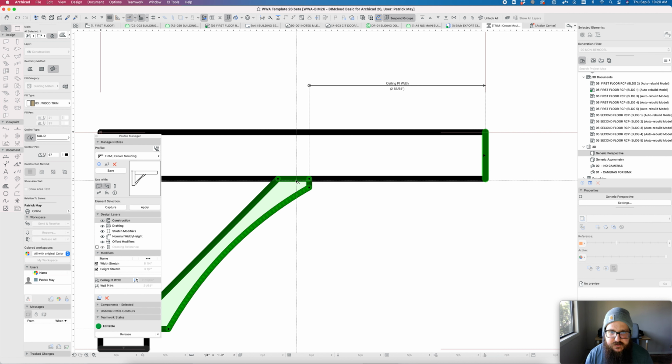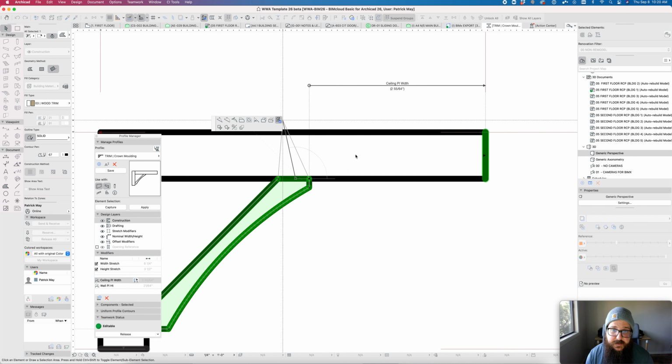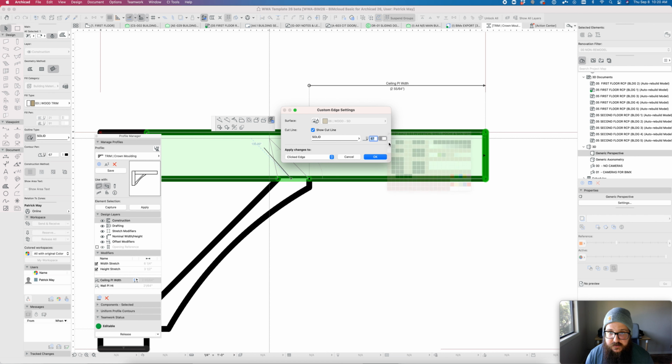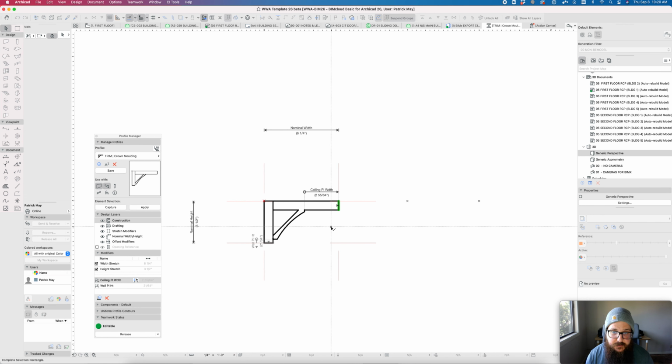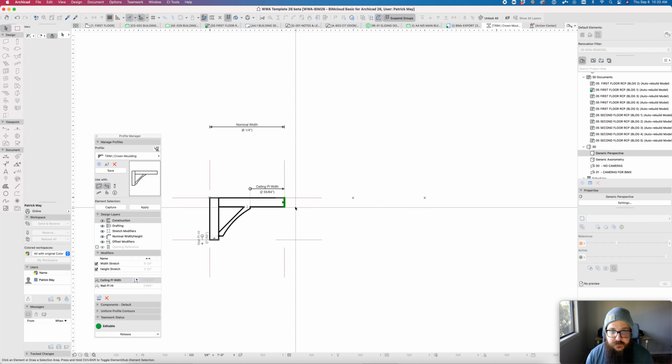And then to meet our graphic standards, if I wanted to adjust individual line segments to be a different pen weight, for example, I want these to show as pen 21. And you can meet our graphic standards that way as well by just selecting certain segments, adding segments, making those segments change line weights for different pen sets. So you can clean that up a little bit nicer. The pens don't have to go away, but they will be that pen weight for that section.